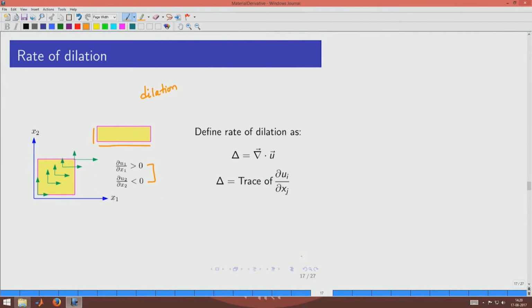Now, you could see that in the x direction it is changing because of dou u1 by dou x1, in the y direction it is changing because of dou u2 by dou x2. So, now you may suspect that in the z direction the same thing would happen, which means that if you were to look at this quantity dou ui by dou xj as a quantity with two indices, then whenever these two indices are matching, you are getting these terms, and these terms are causing the shape of the control volume to change.